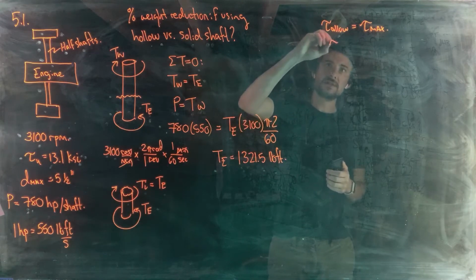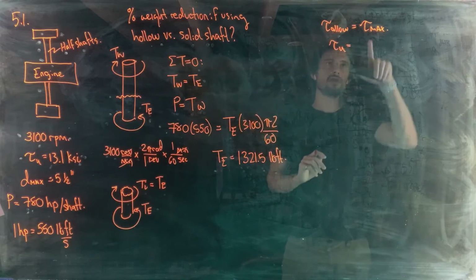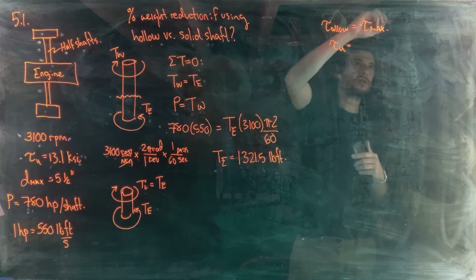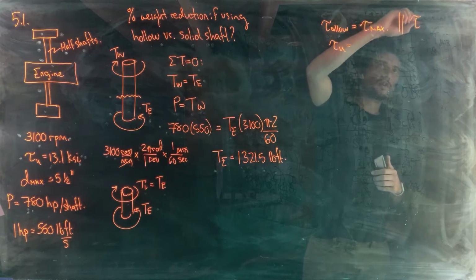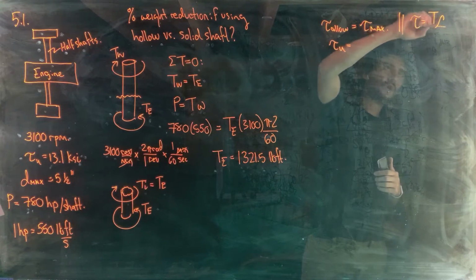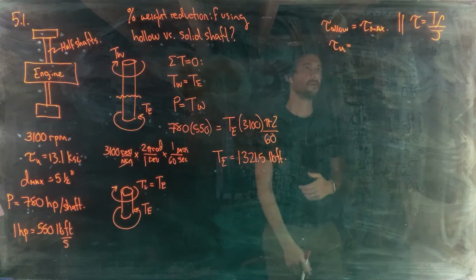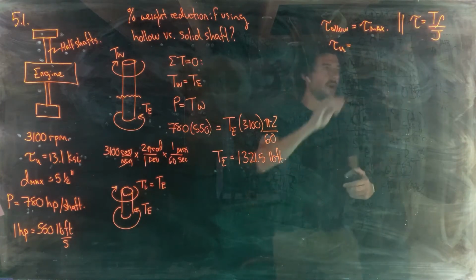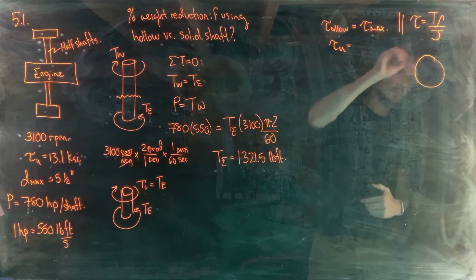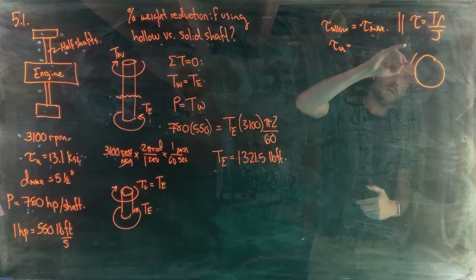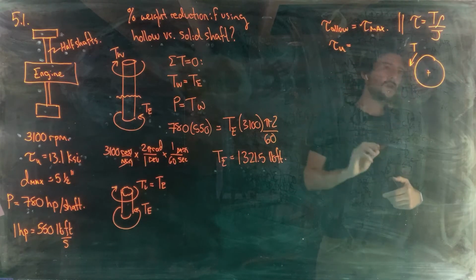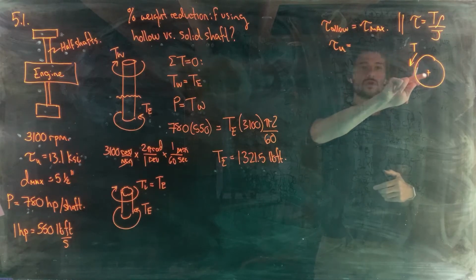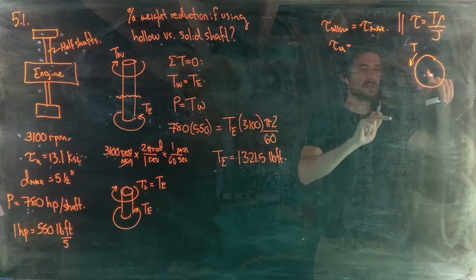So here, this is going to be our ultimate shear strength, and then the maximum shear stress. We've got our equation for shear stress due to torsion as tau is T rho over J. Now, for something that has a circular cross-section experiencing an internal torque, the magnitude of shear stress increases moving radially outwards from the center.